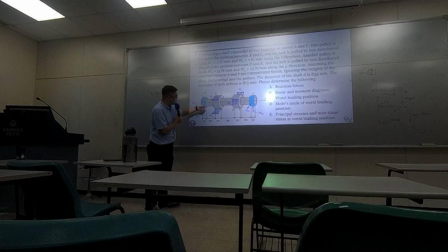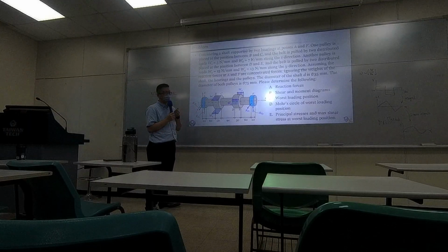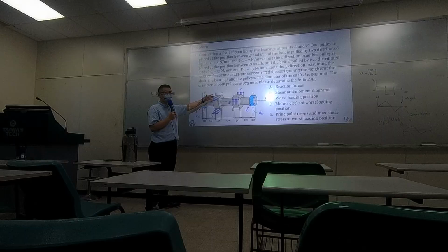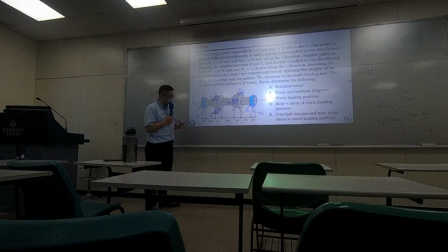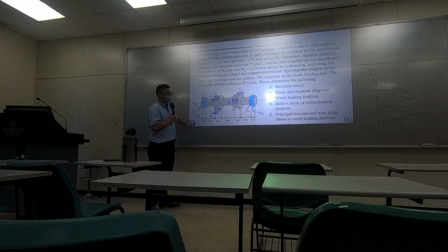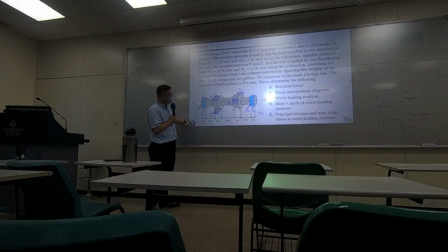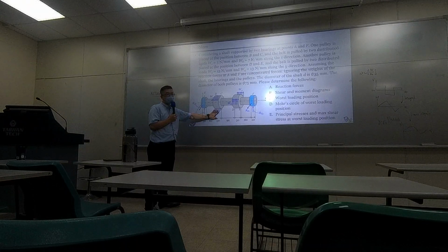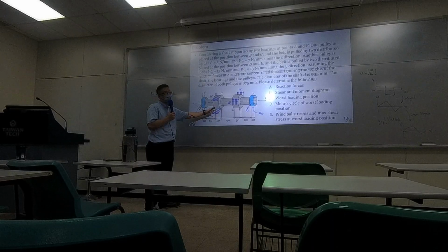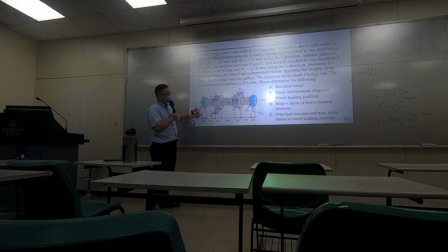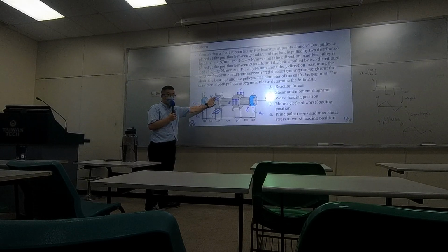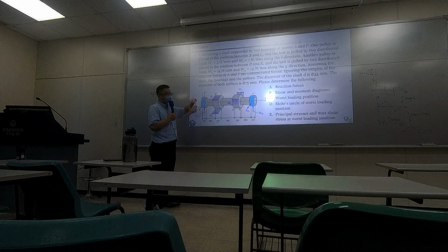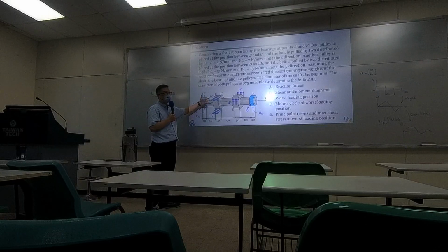Imagine if you are pulling these two with the same amount of force, it doesn't spin, it doesn't rotate. But the idea is that maybe there's a motor on this edge, the motor is driving the belt, so it's pulling one side of the belt a little bit more, so there will be an imbalance between both sides, generating some torque.